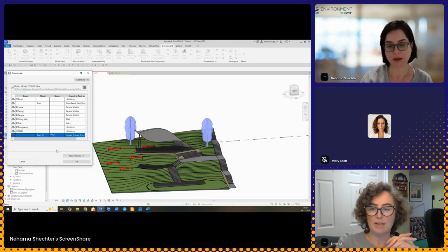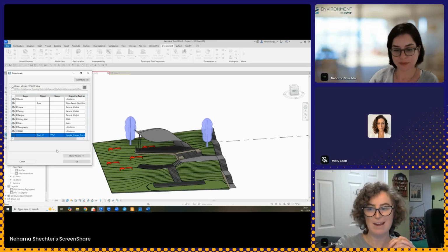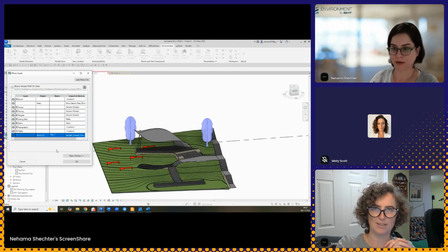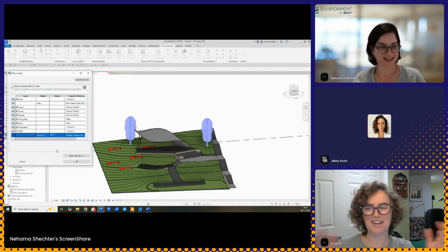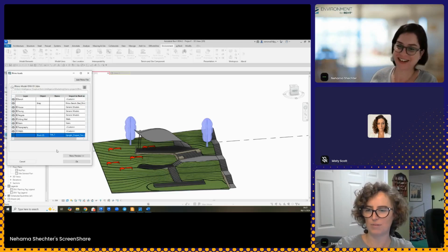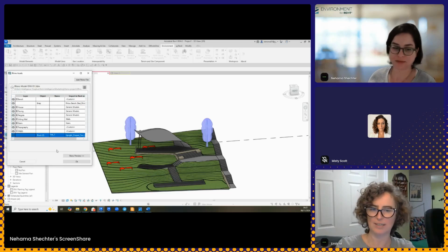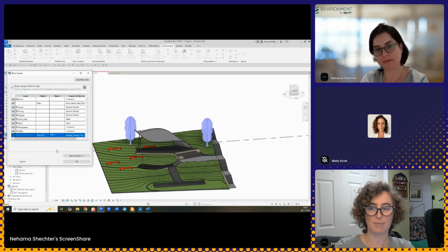There could be some naming schemes that you would put in place on the Rhino side. Whatever you name that block, put an R in front of it, R for Rhino, R for Revit. Anyways, you can pick an initial on both sides or either side that would differentiate something as an imported block versus something that's native in Revit. So that's maybe an option there.